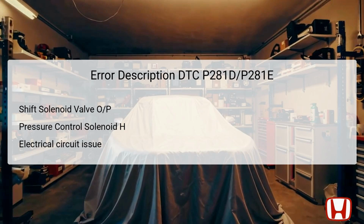The Pressure Control Solenoid is a critical component located within the transmission system that plays a vital role in regulating hydraulic pressure for optimal shifting. Located within the continuously variable transmission, it ensures that the vehicle shifts smoothly and efficiently. An issue here can lead to poor driving experiences, such as harsh shifting, or, in severe cases, no shifting at all. Given that these codes relate exclusively to electrical circuit problems rather than mechanical issues, they require a focus on the connections and wiring associated with the solenoid and the Transmission Control Module, TCM. The importance of resolving these codes cannot be overstated, as they can directly affect vehicle performance.